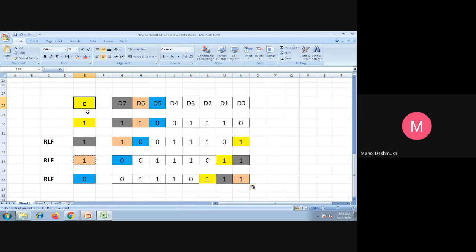If we use the rotate right, then we use carry as a position indicator here, no problem. It is not mentioned or meant like that. The carry is always at the left hand side of the register, file register or working register. So see which operation or which instruction is suitable for performing your required task. For that, you should go with either left or right operation.